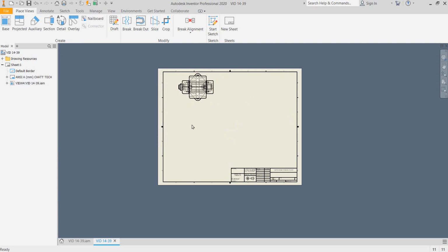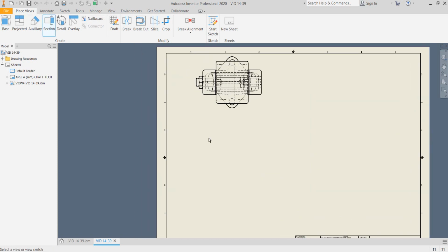And there's a couple of different ways that you can do assembly sections. Here you can put a view in and then section that view and pull it down. Or in your assembly, you can create a section view and save it as a model state and then bring that in. I find this to be the least confusing. It may be the most unorthodox though, but we'll see.